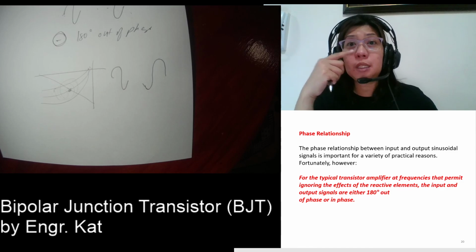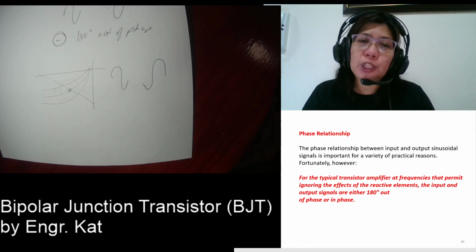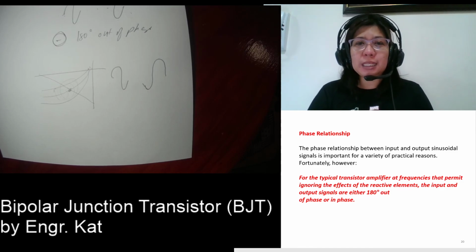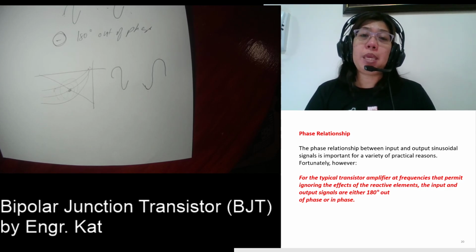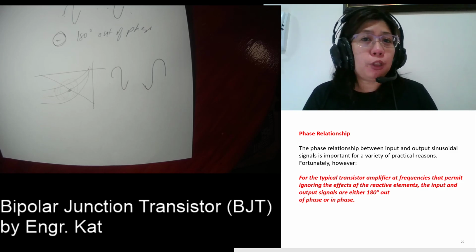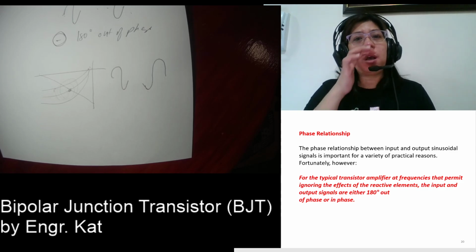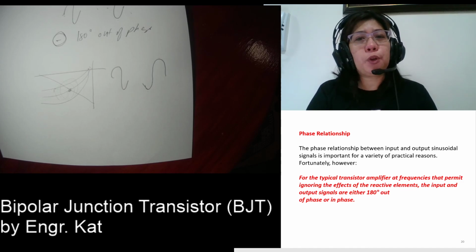Okay, so for this video, we just had an introduction with the AC analysis. So just for a recap, in the AC analysis, we will be shorting all your DC sources. So the only input that we're going to consider here is the AC input.